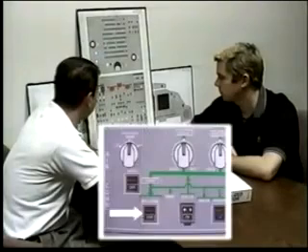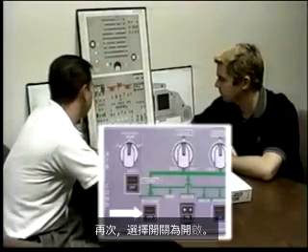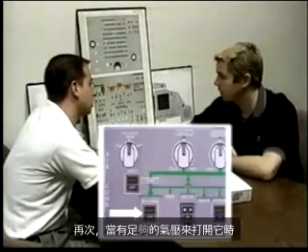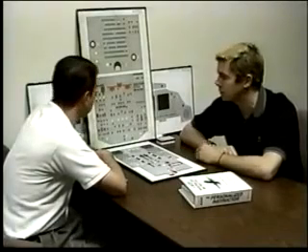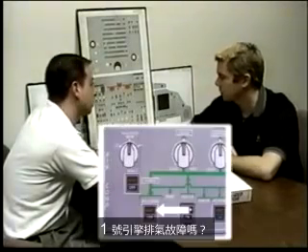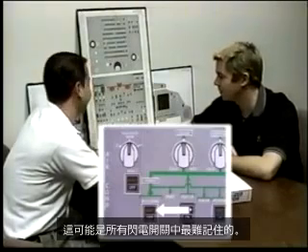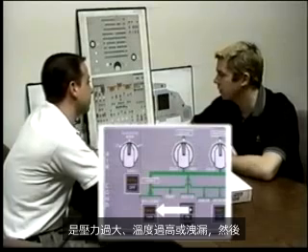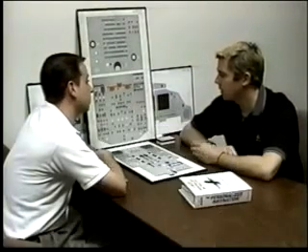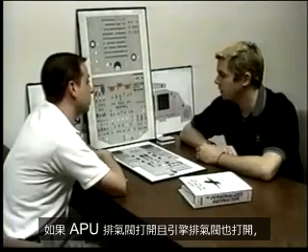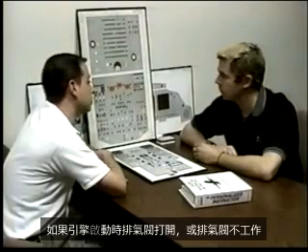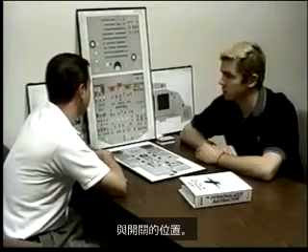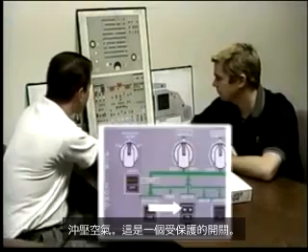Engine 1 bleed. Again, switch is selected to on. When would the engine bleed open? Again, when there's enough pneumatic pressure to open it, as long as the APU bleed is closed. Fault on engine 1 bleed? This is probably the hardest light and switch to remember out of all of them. It's the overpressure, over temperature, or a bleed leak, and then there's 3 valve disagreements. If the APU bleed valve is open and the engine bleed is open, it'll give you a fault. If the engine bleed valve is open during engine start, or if the valve disagrees with the position of the switch.